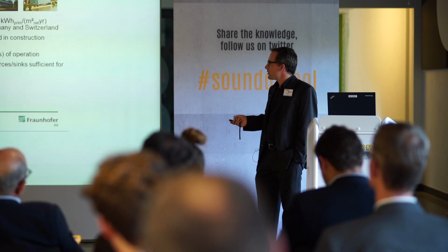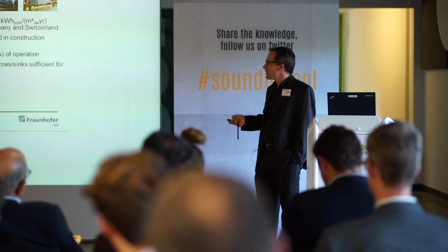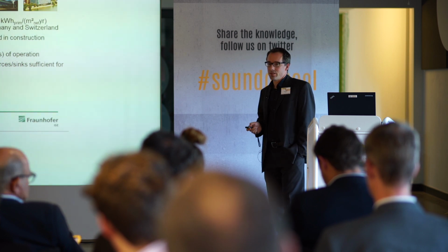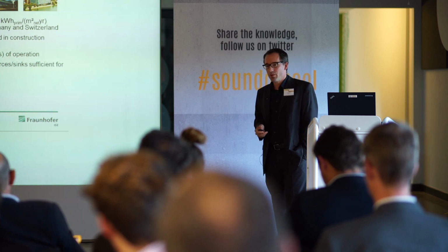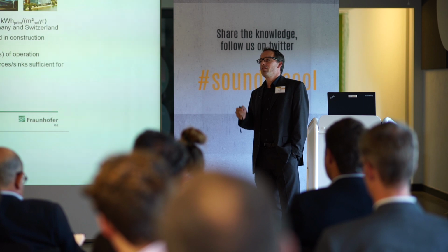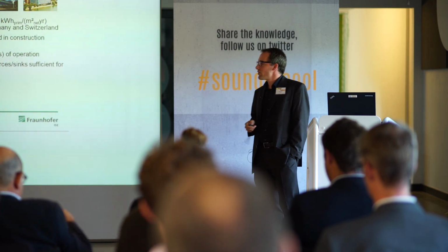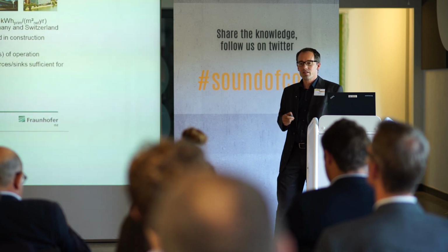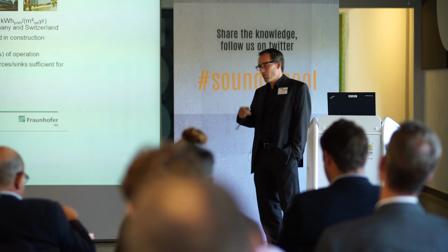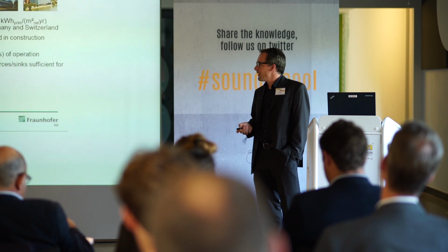One very important thing we found in nearly all of these buildings is that accompanying commissioning is necessary during the first years, because typically these systems are not behaving the way they are planned from day one. So we have to measure and rate these systems during at least the first year, or even better, continuously.